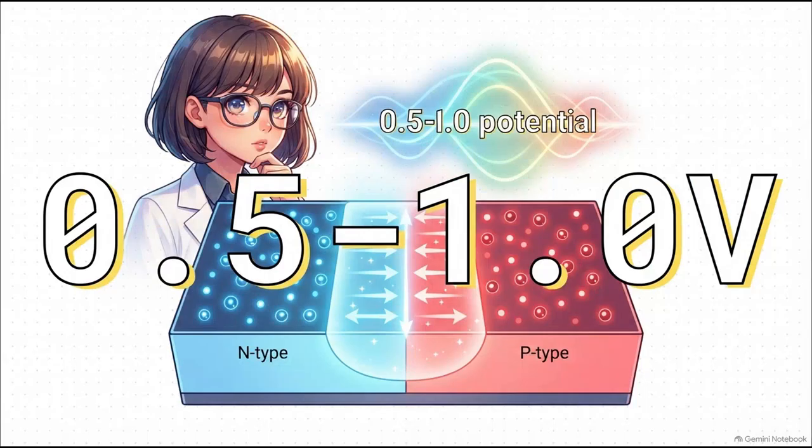of charges. And this invisible barrier isn't just some theoretical concept. It generates an actual, literal, built-in potential difference across the depletion region of between 0.5 and 1.0 volts. This electric field stops any further flow of charge across the junction. It just sits there in perfect equilibrium, like a microscopic dam holding back a massive sea of electrons, just waiting for us to apply an external voltage to activate it and control the current.